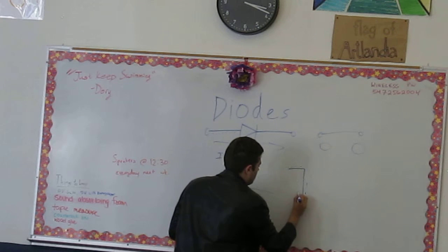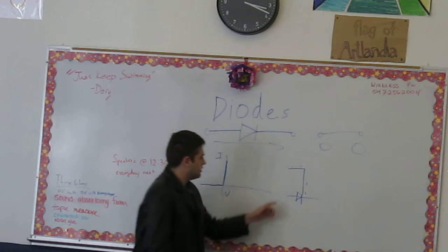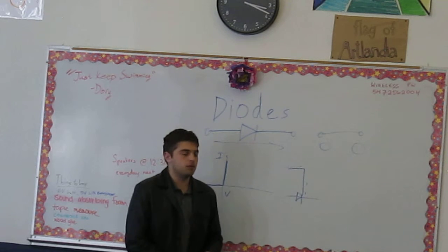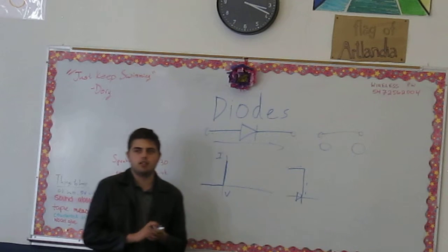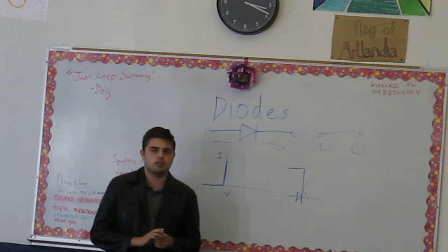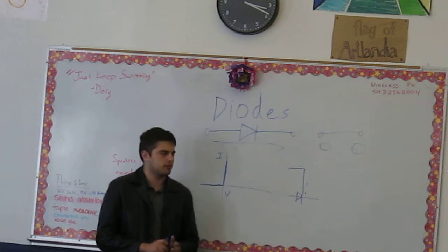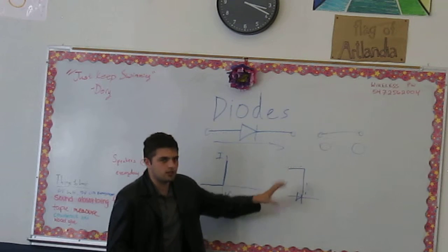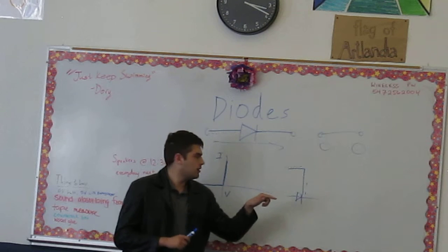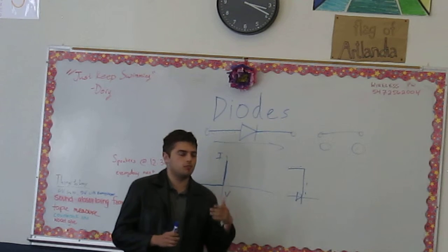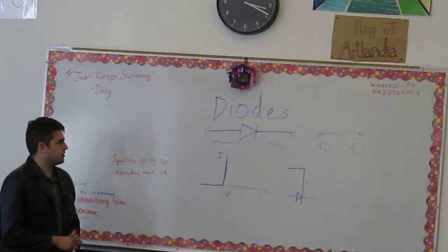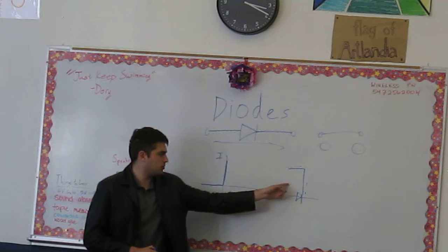So you can fall off the cliff easy, but coming back this way, you can't get back up the cliff. Of course, you can get back up the cliff if you have a ridiculously high amount of voltage. That's like on the reverse current, where it'll break down at about 75 volts. So let's say it takes 75 volts to get across this big cliff, and going this way theoretically would take none, because theoretically it works perfectly. So that's the ideal case. That's what you can think of going out the energy levels.